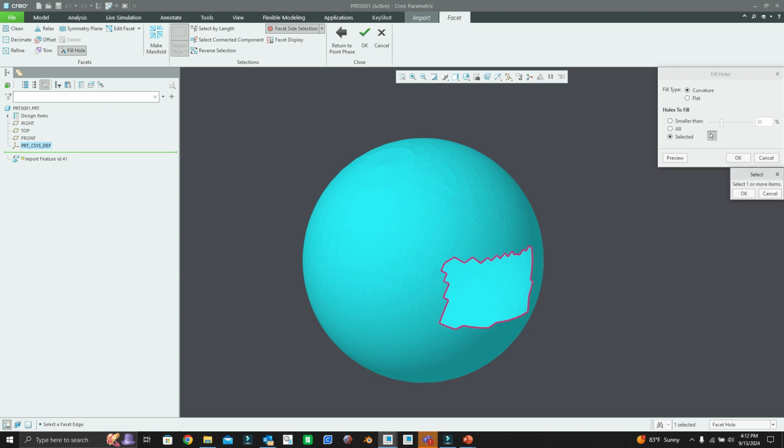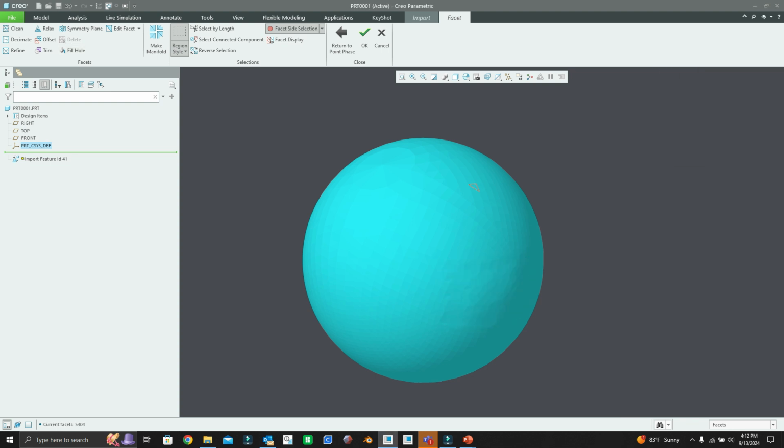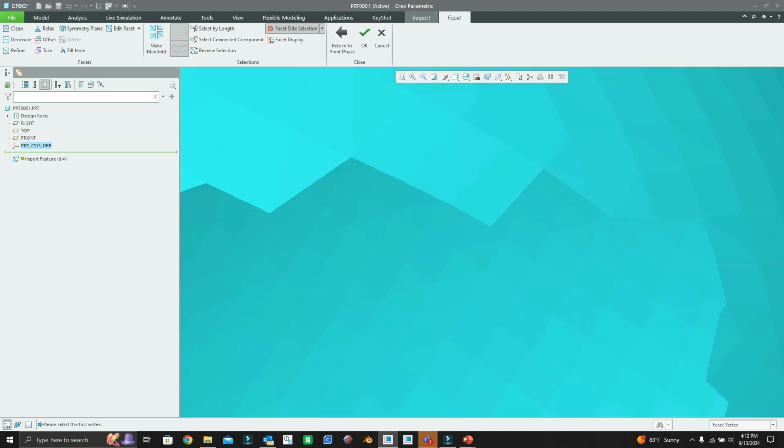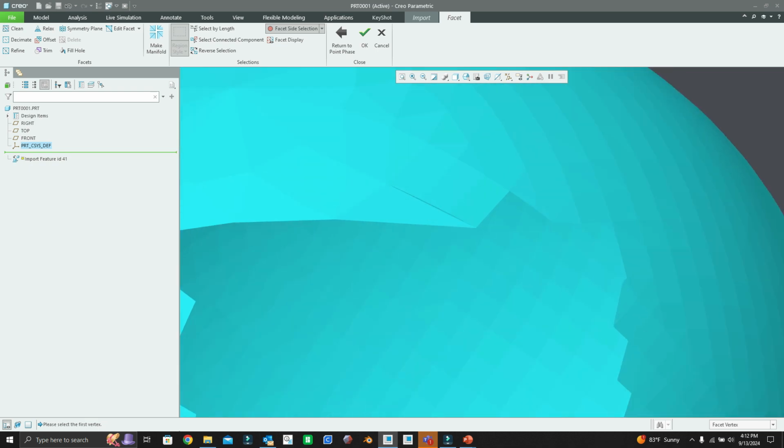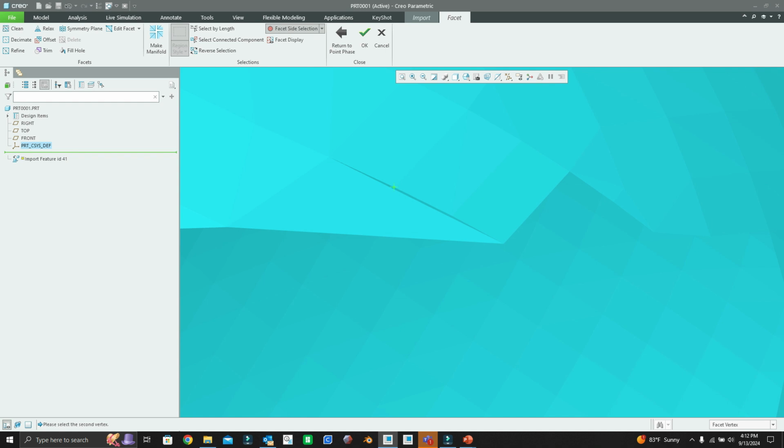Make sure I select it first. Okay, great. I also have the option to create triangles or polygons, right? So there's add facets. I can come in here and click the endpoints of the mesh and create some polygons, and start cleaning the mesh up here.